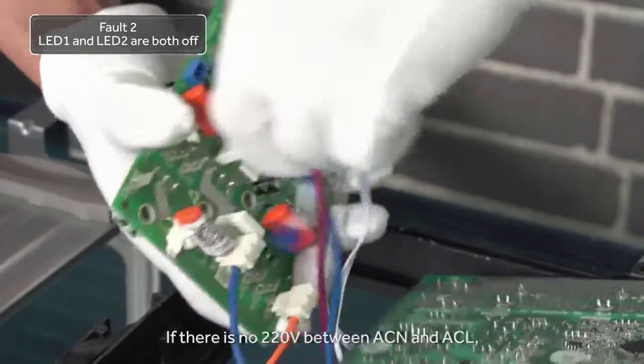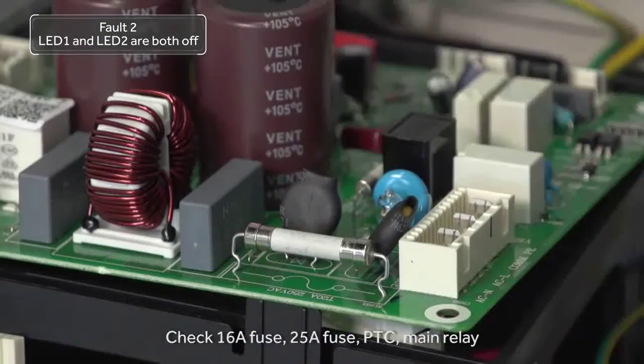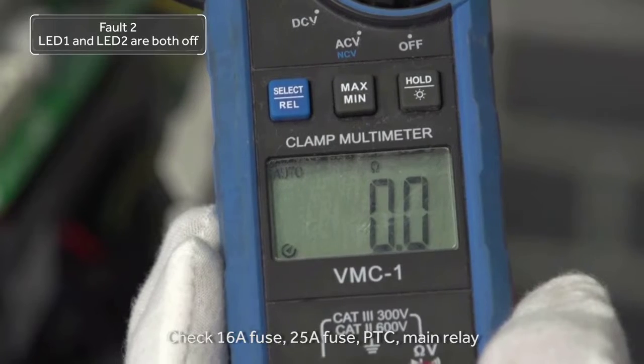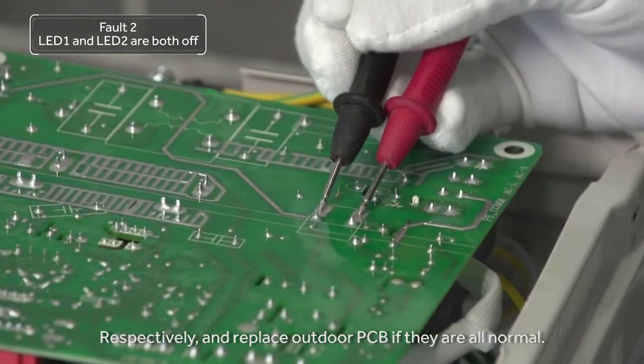If there is no 220 volt between ACN and ACL, check the 16 ampere fuse, 25 ampere fuse, PTC, and main relay respectively, and replace the outdoor PCB if they are all normal.